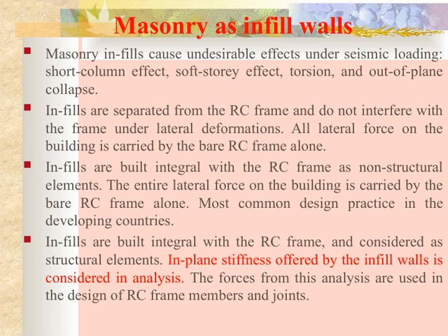This is a common approach, especially in developing countries, where infills are built as non-structural elements. In this configuration, the infill walls are essentially part of the building, but don't contribute to the structural capacity. They don't help carry lateral loads. The entire lateral force in the building is managed by the RC frame alone, which simplifies the design but can have implications during seismic events.